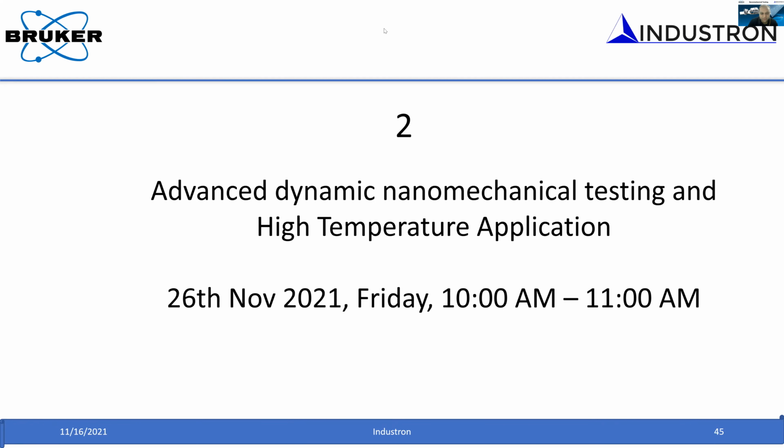First question: how do we define quantitatively the relative elastic or plastic nature of a particular phase in a multi-phase material via nanoindentation and nanoscratch experiments? Well, in the last part of my talk, I gave you some examples where you use the in-situ SPM imaging to see those particular phases or the microstructure, and then you put the probe onto those microstructures and measure the load displacement response.